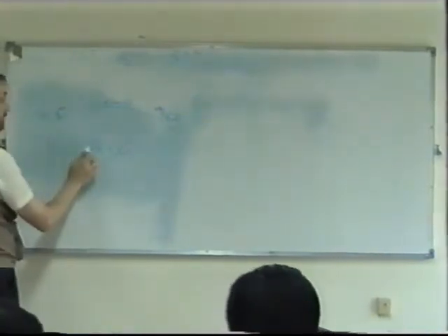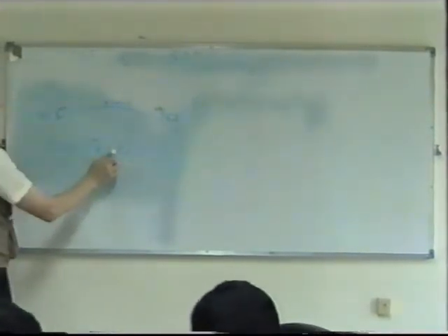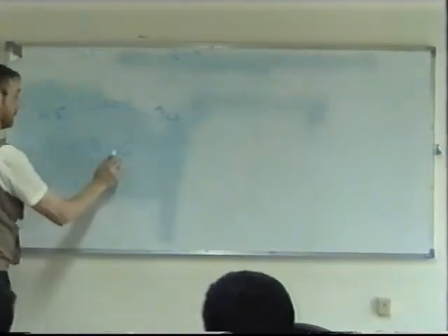And that's the formula which we can use. Let me just say it in words what we have here: 3570 multiplied by the square root of the height of the transmitter plus the square root of the height of the receiver antenna.